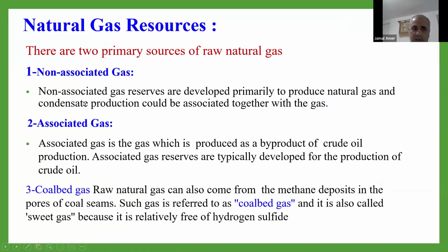Dry gas is just dry gas we receive, while with wet gas we receive gas with some condensate, and we have to separate this condensate and any water vapor from this gas during the treatment. Associated gas is produced with the oil, and as I told you, it is a source of energy that moves the oil from the reservoir to the stations through the wellhead and pipeline.